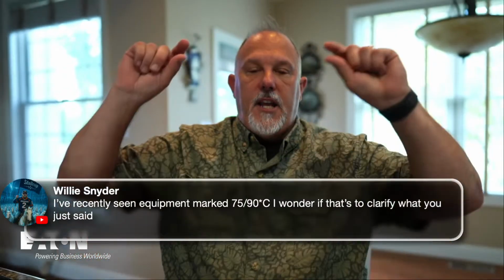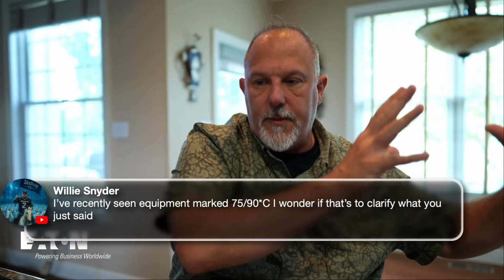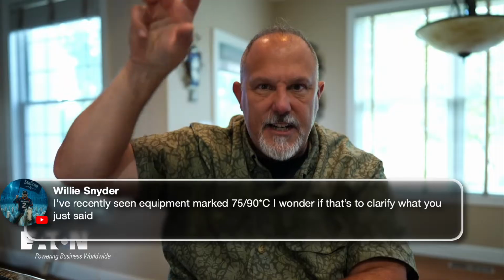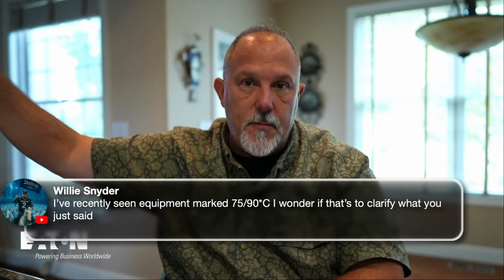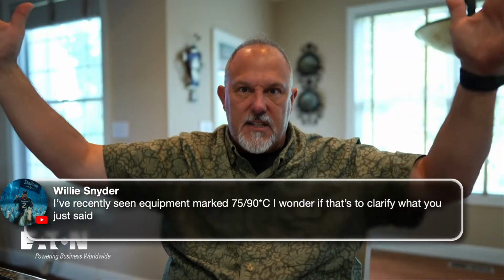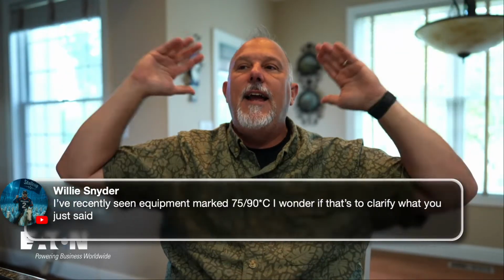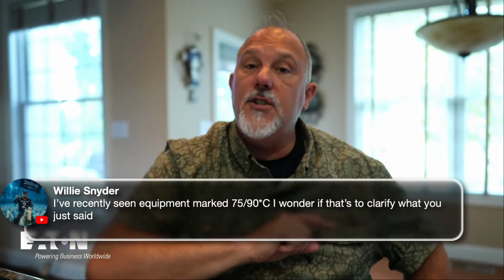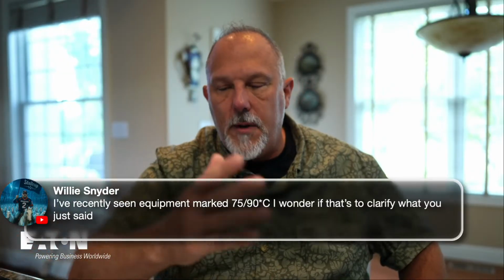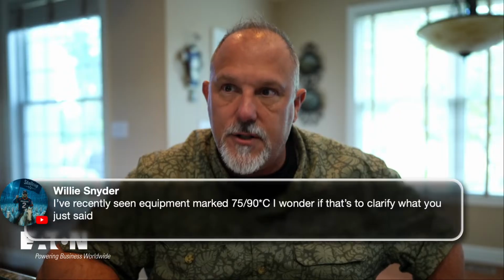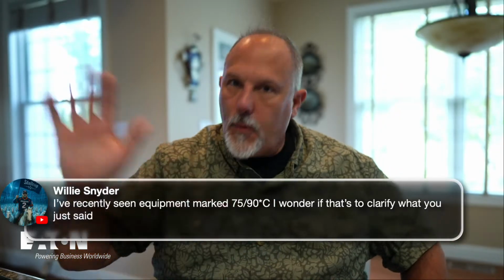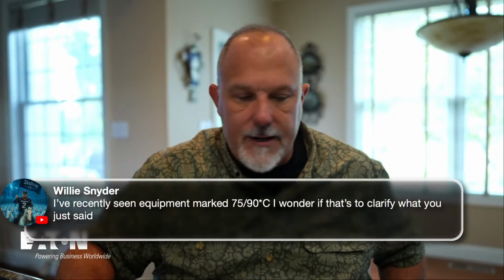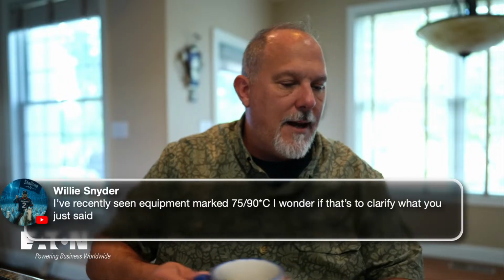Because here's the thing. If I go from a 75 degree C equipment up to a terminal, like a box that has a terminal block in it, and it's 90 degrees C, and then go to another terminal block in a box that's 90 degrees C, that conductor in between, I can use at 90 degrees C ampacity every day of the week, twice on Sunday. And I don't need a code change to do it, because that is all per existing requirements. I know we made a change in 210 or 215 that says you can do that. Not needed, but we put it in anyway. That's fine. It added clarity, but it wasn't necessarily needed. But Willie, I'd love to see that information. Love it.